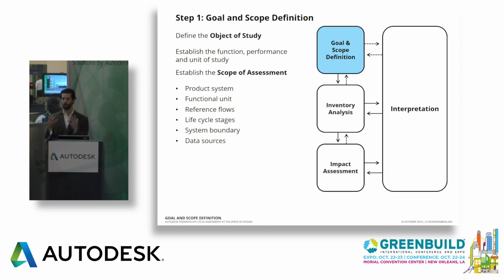What exactly are you trying to study? And the key thing in the context of applying life cycle assessment to architectural practice is determining your functional unit. And your functional unit is essentially your unit of comparison or unit of assessment. And what your functional unit has to be is something that, if you say you're comparing two options, these things actually perform the same function over the same time period. So let's say it's a certain amount of insulation that's rated at an R value of 5, and it's supposed to last 30 years or something like that. That's your functional unit. So no matter if you end up varying your materials, the shape, dimension, what have you, it has to achieve that particular objective, that functional purpose.